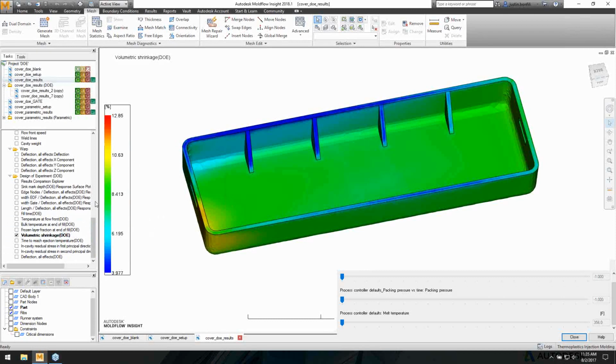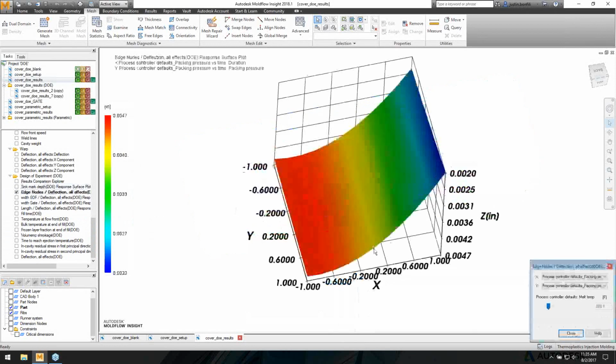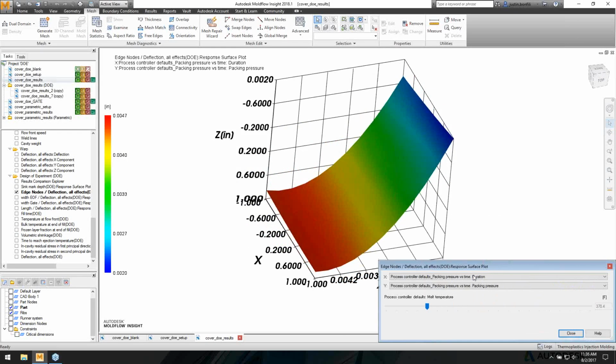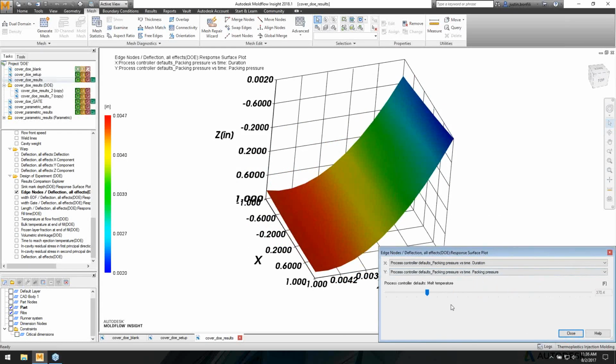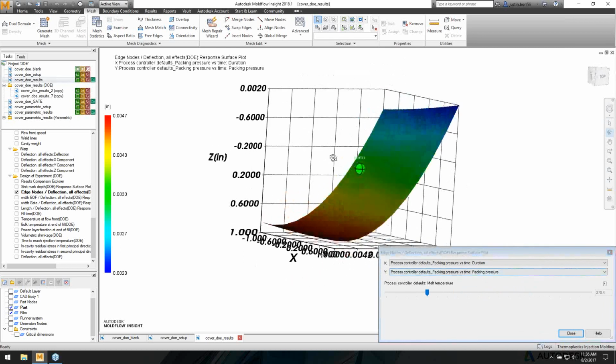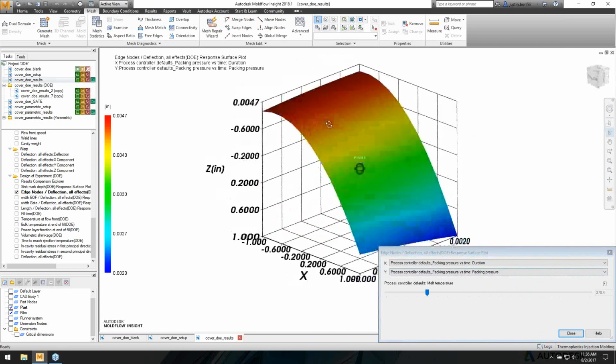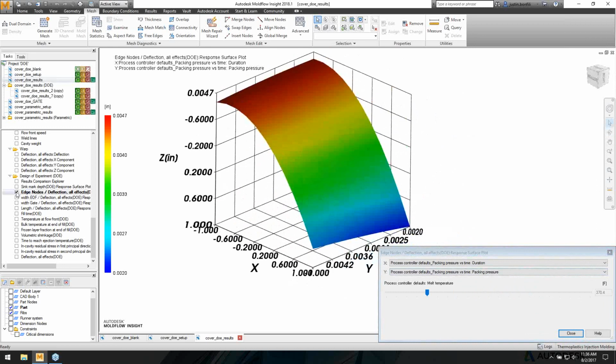So there's also response surface plots that are added as well, and these are for the specific quality criterion we have set. And these plots will show the top 3 influences, and it'll show the effect that 2 variables have while keeping all of the other variables constant. And a good way to set this up to look at it is to orient your z-axis, which is the quality criterion that you're investigating, to be vertical, and from low to high.